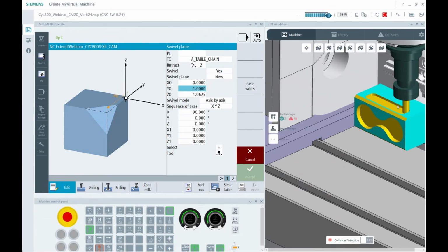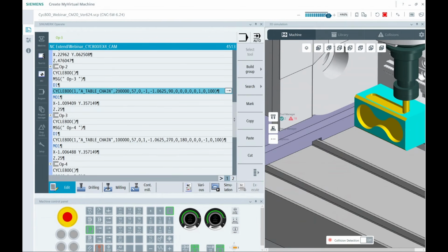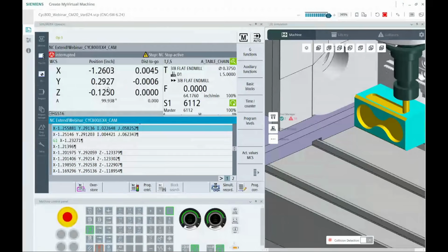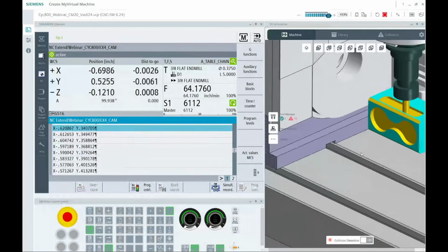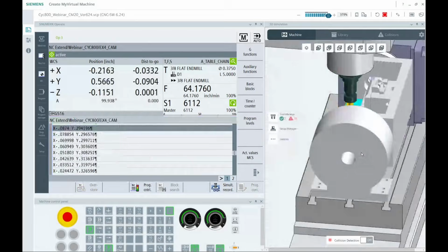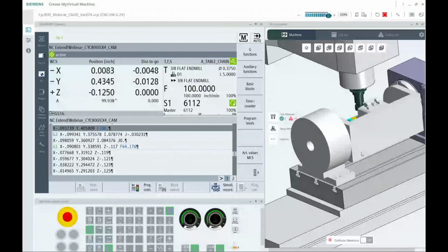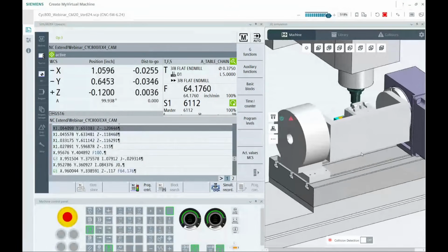So I personally like to be able to see my features from probably where they were dimensioned from. But that's all a behavior of this. If your CAM system's not doing it, it's okay. Just keep in mind that when I look at the display, it's going to be a little bit harder to read, right? Okay, so there's the pocket, and at the end, we did shove in that little offset there.